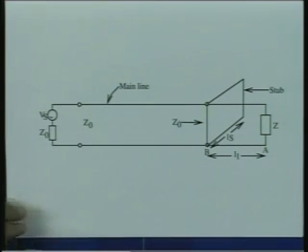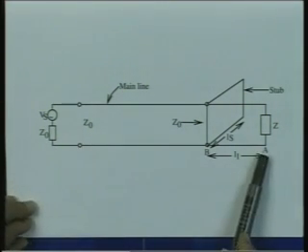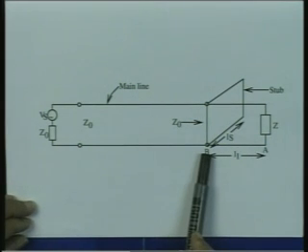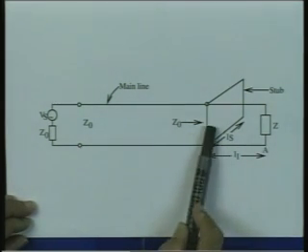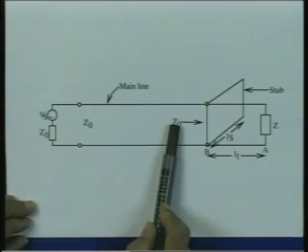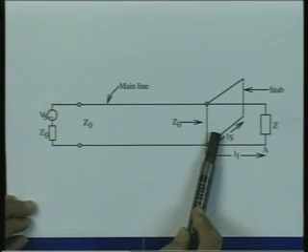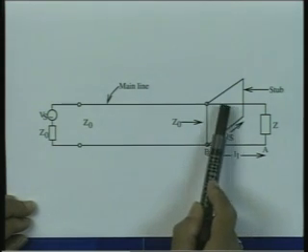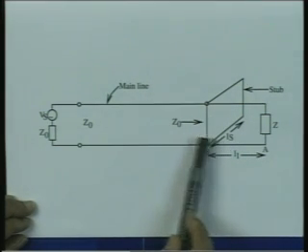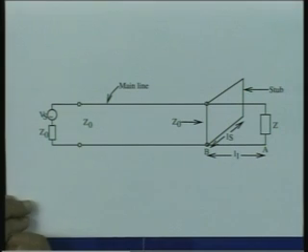I achieved the matching. So, the problem is now as follows: find this length L1 such that when the impedance is transformed here, its resistive part becomes equal to the characteristic impedance and it has some reactive part. Choose the length of the stub in such a way that its reactive part cancels this reactive part. So, the resistive part is equal now to the characteristic impedance beyond this point.